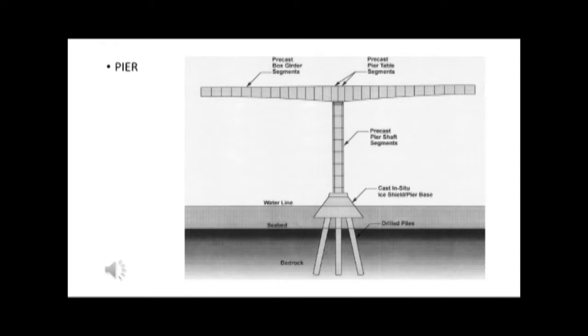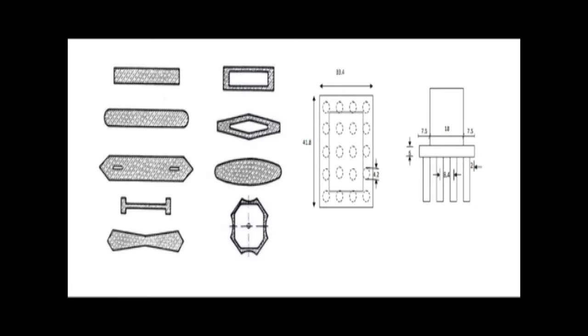On slide number 36, we are understanding piers. Here we have the cross section of the pier. A pier is an intermediate support in the bridge structure. It supports the deck slab of the two spans. It's a resting place of the deck slab of the two spans, and it carries the load in a simply supported manner, in a cantilever manner, or in a continuous manner. In all of these manners, it acts as the intermediate support of the deck slab, beam, truss, timber beam, timber truss bridge, or whatever we have here.